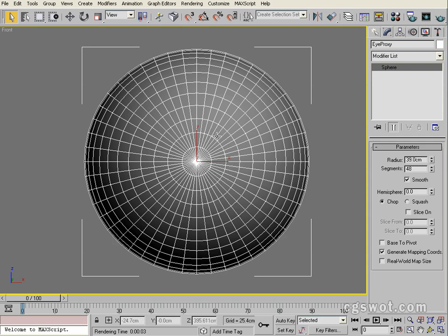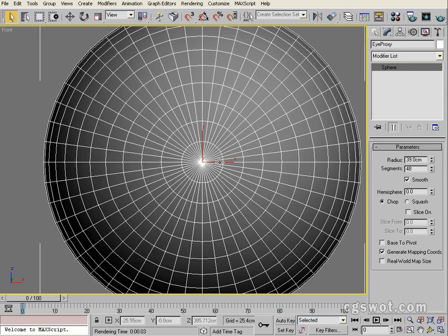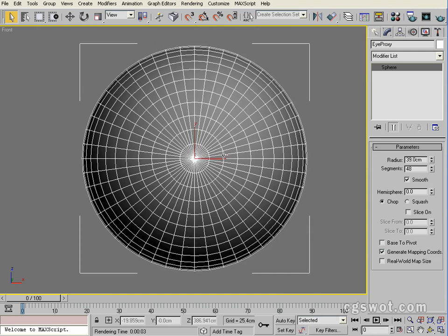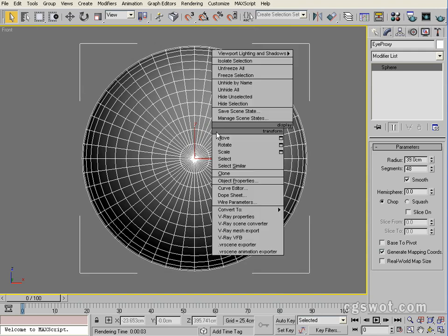We're going to select a section, chop it out, flip it around, and we need to weld the vertices back together, and so the fact that it's uniform in these quadrants is going to make that task far more doable, and it's going to make it work nicely.